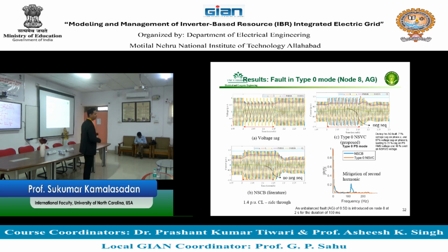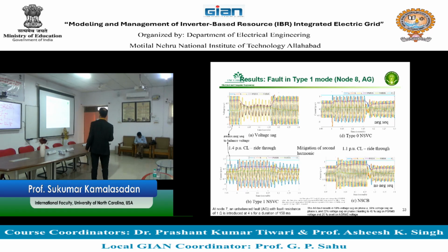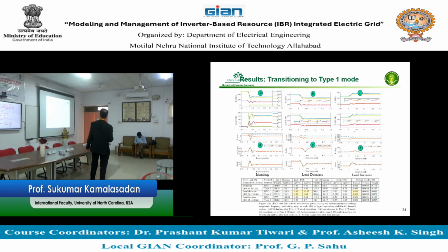Anytime when you work on the inverter, looking at the inverter side, what did I tell you? Look at the waveform. You don't do any other things. So now you can see this is a ride-through fault. Ride-through is another thing that is mandated by the grid code, which is 1547. So you can do fault ride-through capability. It's an unbalanced fault with fault resistance of 1 ohm, and you are looking at how much ride-through capability the inverters have and how the current and voltage waveforms vary.